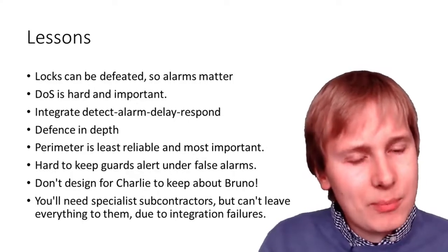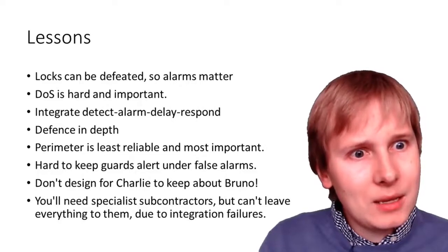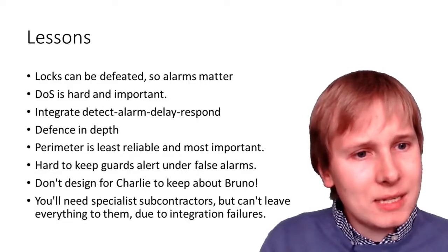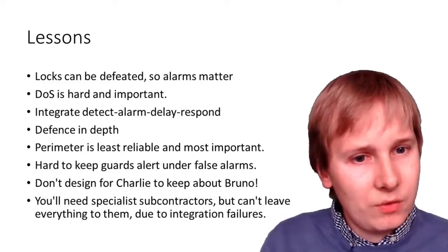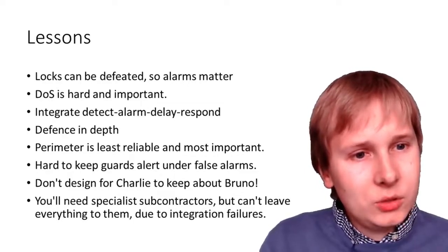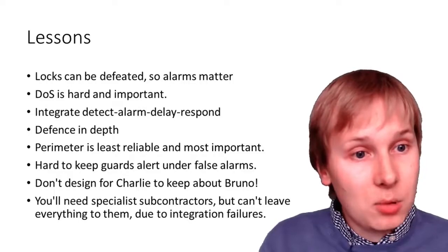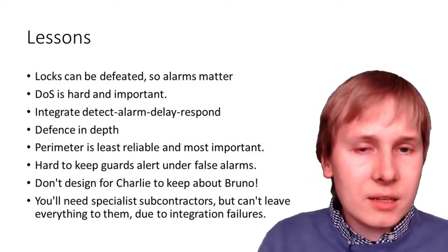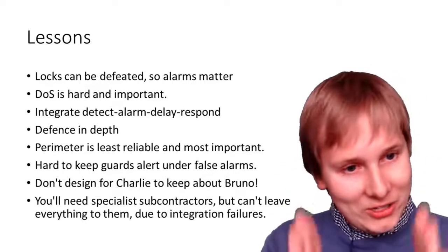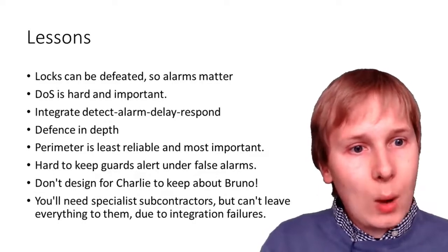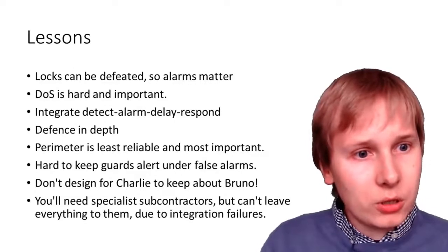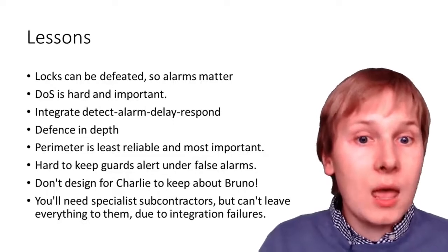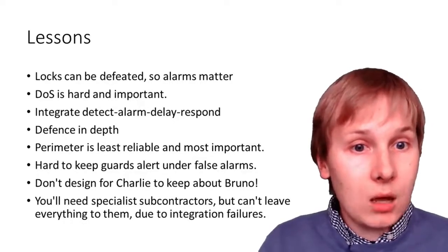Don't design for Charlie to keep out Bruno. If your attacker is going to be more sophisticated than someone who can bump a lock, then you need to have a security system to match, rather than assuming that a few padlocks will solve the problem. And you'll need to take advice on this. You'll need specialist subcontractors to implement a well-integrated security system, but you can't leave everything to them. Each one will be in their own vertical silo, and so you need to have specialists on your team. You need to have experts on your team who can integrate between all of these different subcontractors to get security systems that really communicate with each other and actually can implement detect, alarm, delay, and respond.